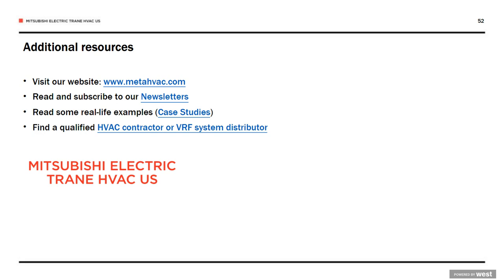The other place that I wouldn't recommend using it is in big box stores. I mean, VRF for a Best Buy or a Home Depot or these large warehouses, it'll work fine. It'll work great, but it's overkill. It'll cost too much to do that. There are other systems that'll be less costly to heat and cool great big spaces like that.